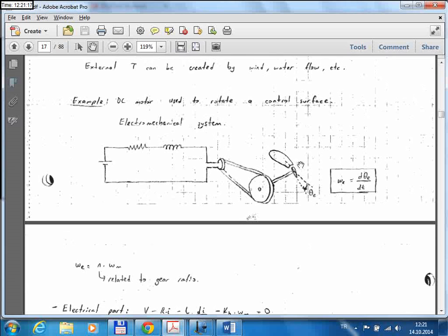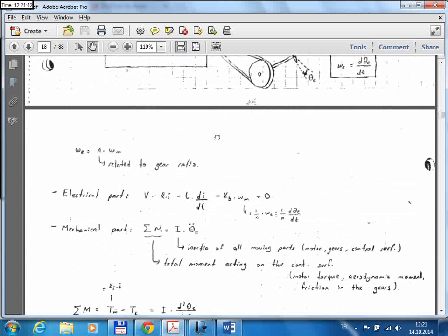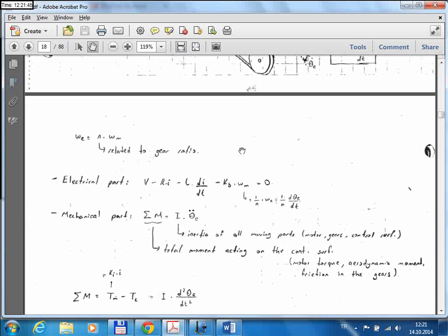Okay, so there's a mechanical part which can rotate. That means there should be a moment of inertia for that part. So there's a mechanical inertial element here, right? So we need to write a second order differential equation for this part, and then we need to write the equations for this electrical part. So you see those equations written next.